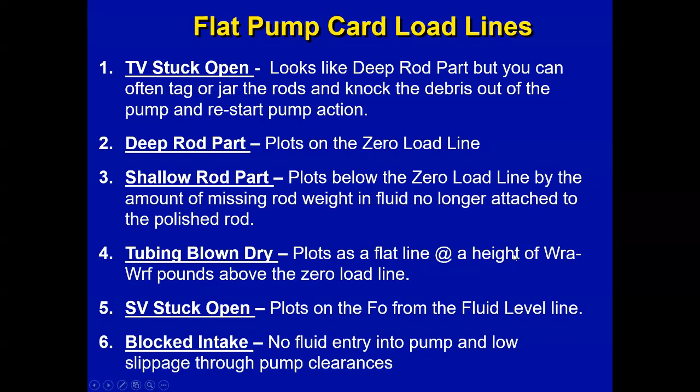So how do we know which one of these dyno cards we are facing? Well, you will have to check all the conditions. Is the well producing? How does the pumping unit look when you stop the pumping? Is there any fluid coming in the backside? Do you normally have severe gas interference? Were you having gas interference, or a pump off condition that may lead to a parted rod? Is a parted rod a common problem in your wells?